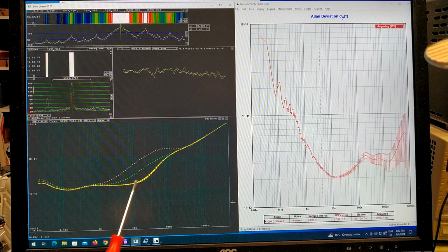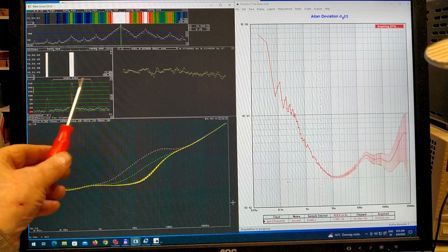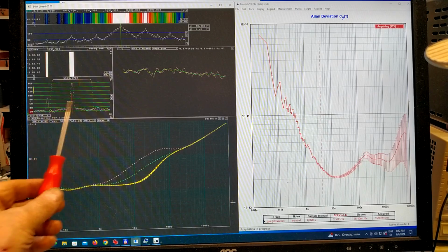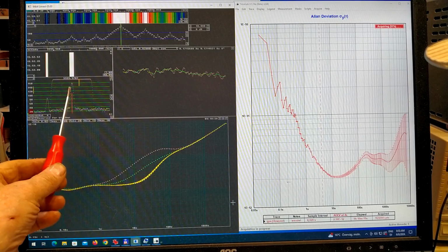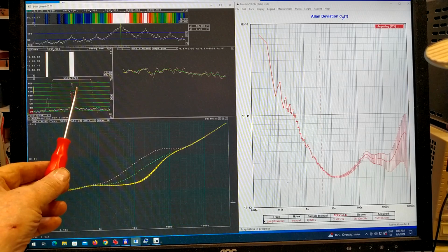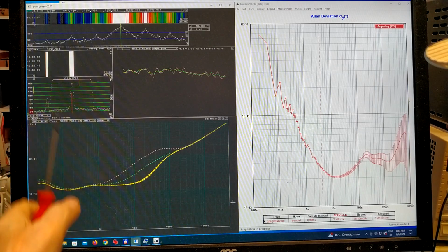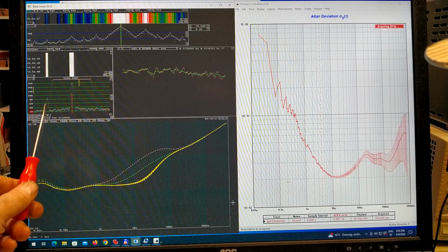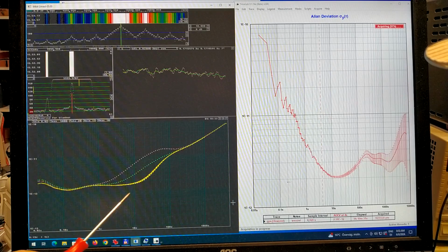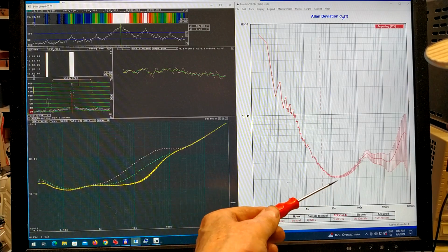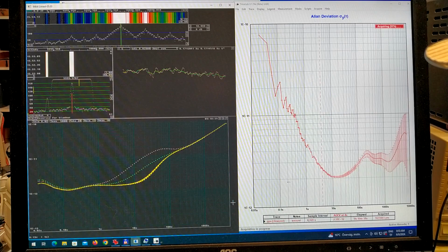And what we see here is not really Allan deviation. It is modified Allan deviation, because here is a filter that removes everything outside plus or minus maybe 22 hertz or so. If I would open that filter, and if I could be without this spur, there would be a little bit more noise. And then maybe it would be in agreement with the Allan deviation.